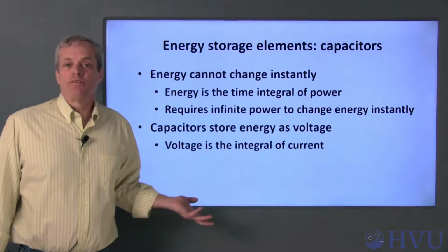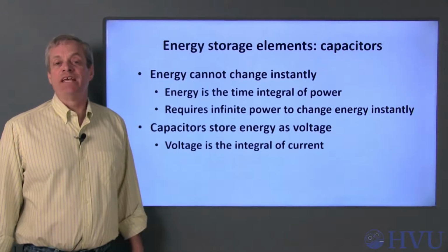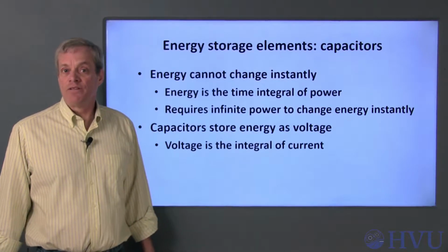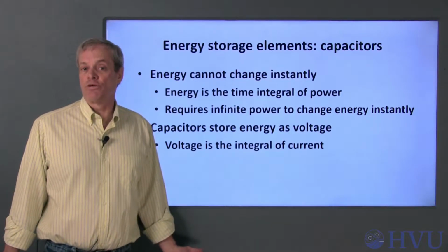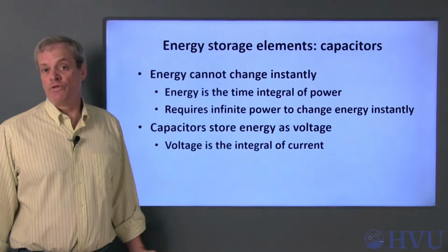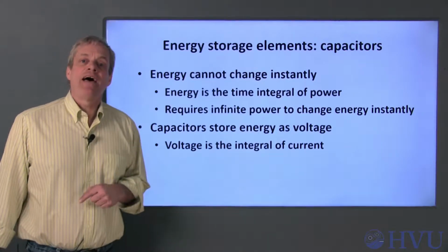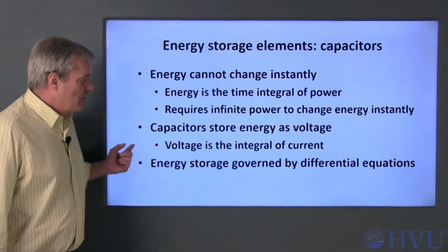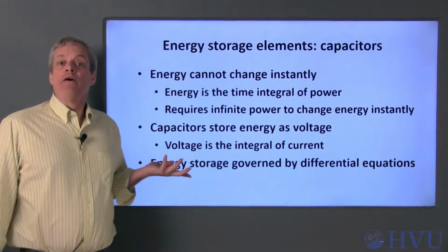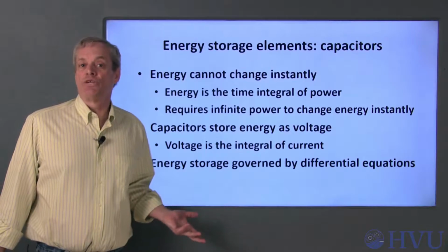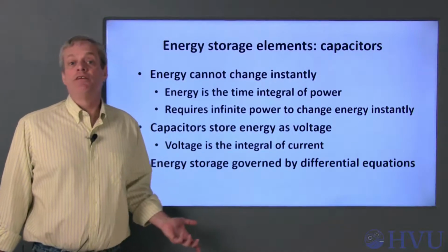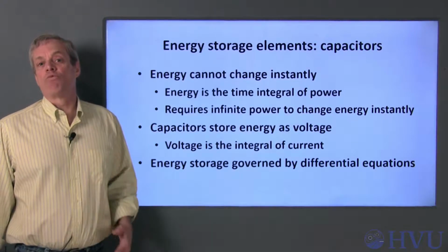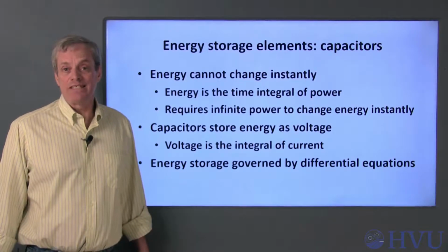As we'll see later in this video, capacitors store energy as voltage. We'll also see that the voltage across a capacitor can be determined by integrating the current through the capacitor. That means that a capacitor cannot change its voltage instantly. Since energy is the result of an integration, the equations governing energy storage are differential equations. Differential equations essentially govern the rate at which energy can be stored in a system.